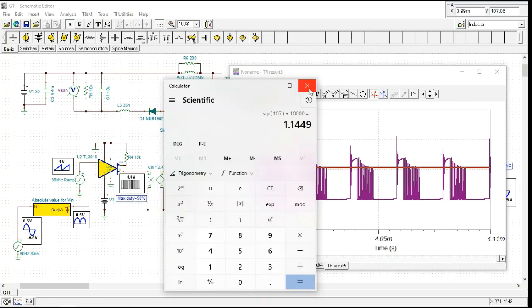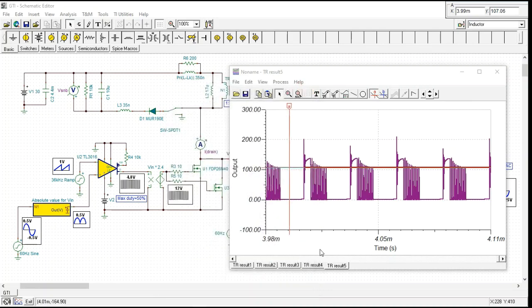So I could definitely lower that resistance, suck up another half watt, and bring that spike down probably into the 200s, dropping at least another 20, 30, 40 volts from what it is now. But I'm not going to do that, because it's still in a safe operating area right now, and I don't want to lose another half a watt if I don't have to. Besides, this is just a breadboard anyway. But this is showing you, if you wanted to eke every little ounce out of it, this would be the snubber. In general, snubbers are power wasters.